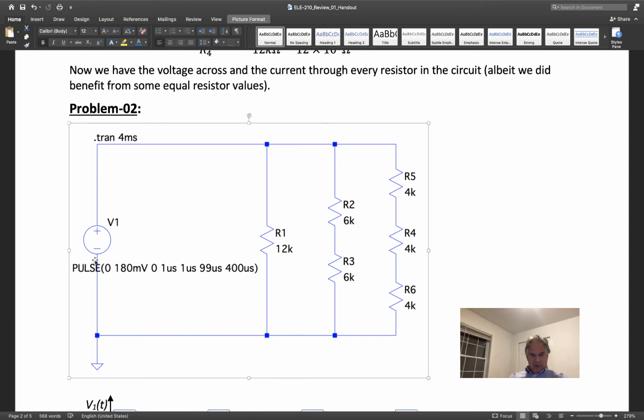Similarly, in this bottom node, which extends from here, include ground in it if you like, up to here and here and here, it's all one node, you've got 15 microamps entering from three different paths, combining to 45 microamps and returning.